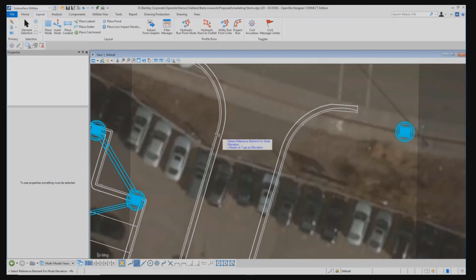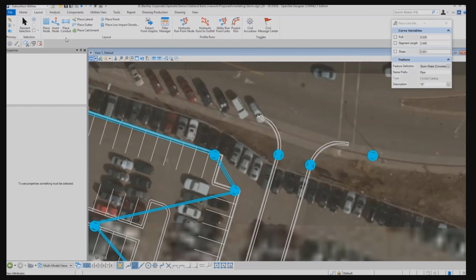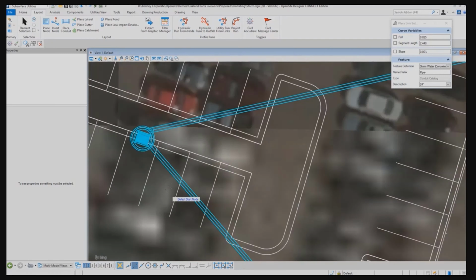Okay, in this second example, we will see how this design intent and civil cells help to streamline the design process of a drainage network. So basically, we select the manhole and we place it in the specific region in which it is needed. As you can see, the manhole is defined to be placed in association with certain elements, in this case, the gutter generated between the curb and the pavement.